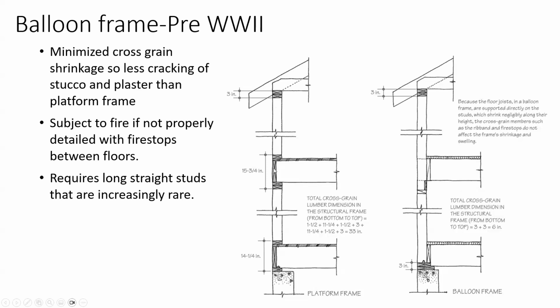The problem is that, were you a firefighter? Okay, so you've got one stud all the way up and it's got boards on one side and plaster and lath on the other. If a fire got into that wall, there was nothing to keep it from running up like a chimney and burning the whole house down very fast.